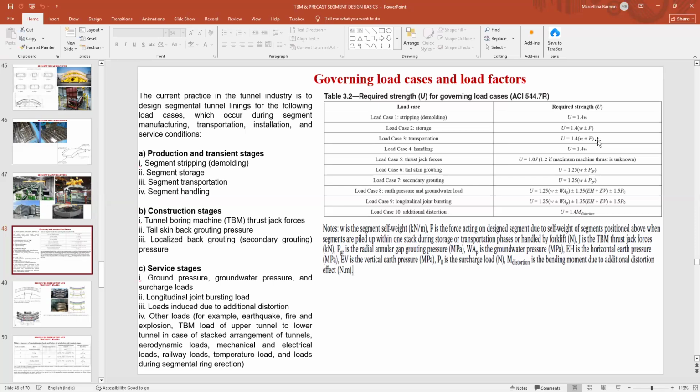So we find that during the launching, during the TBM movement, or after the TBM has gone away, several segments get cracked. Now the cracks can be at different portions. Sometimes the cracks develop at the bolt pocket, sometimes at the trailing edge, sometimes at the leading edge, sometimes at the body of the segments. It depends on the nature of the cracks.